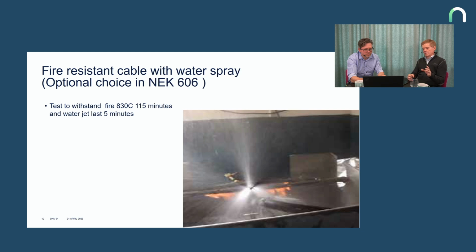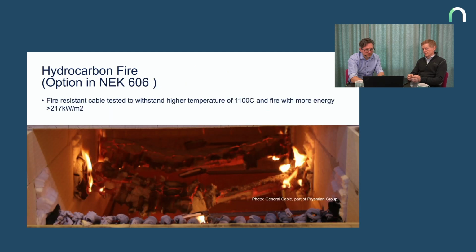The burnt cables are exposed to a water jet, and if they pass this test, we are, let's say, more confident that the cables will also survive the firefighting efforts. But this is optional, this is an extra test. It's not mandatory on ships.